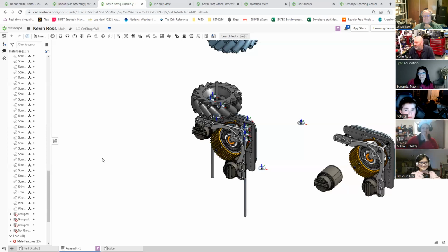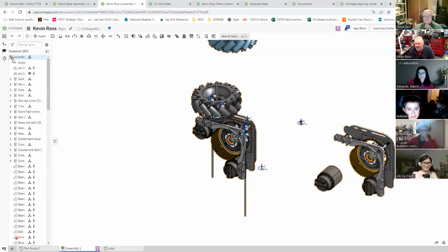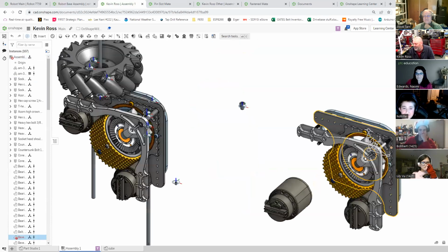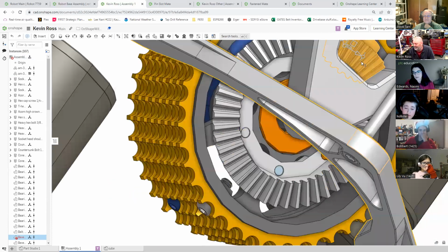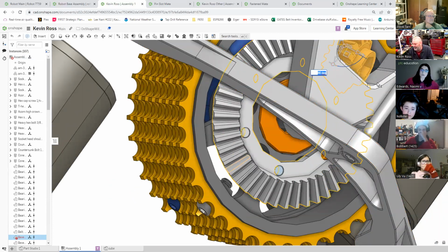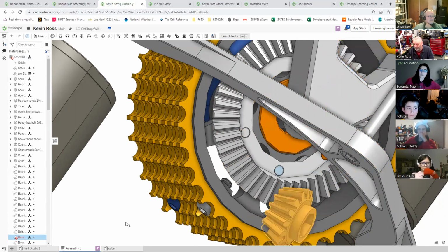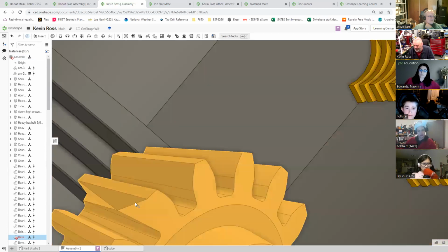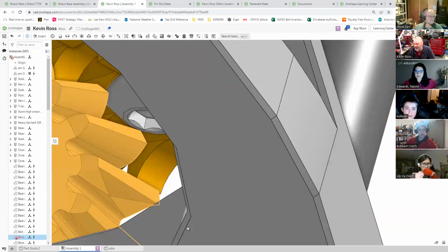For example, if you were to download the Swerve Drive module off of the Swerve Drive Specialties website, it turns out that there's a topology error in a couple of places, and when you insert it, you end up with this red thing of doom right there. All of these have topology errors, and that's where these are coming from. And it turns out it's this bevel gear right here. I think I can drag this out. Yeah, I should be able to drag that out. Okay, come out here. I downloaded this from their website about a week ago.